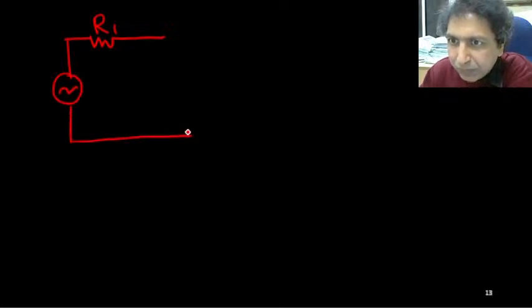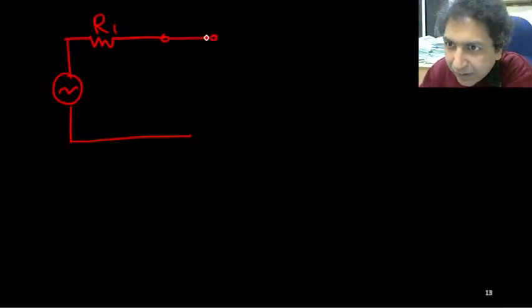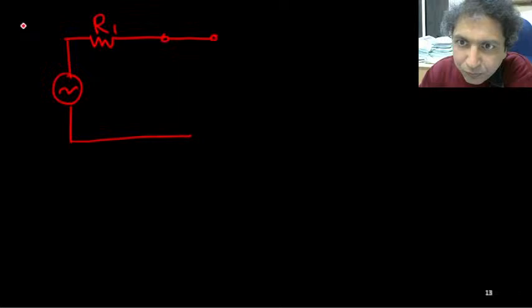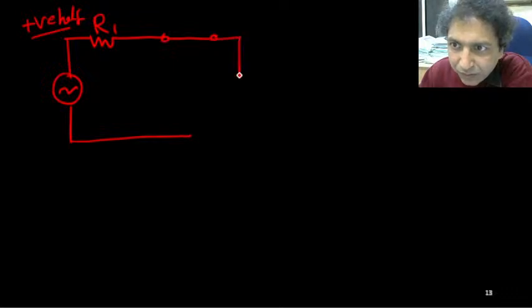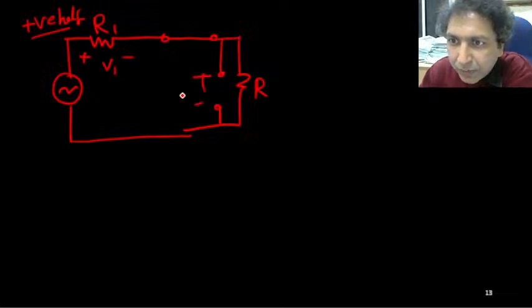This is your R1 and this is the input signal, and I have said that this diode combination, the parallel combination, is always shorted for both positive and negative. Okay. So now if I consider the positive cycle, positive half, and I will redraw this one for the negative half. So in the positive half, D3 is off, so this is off, this is also R. This potential is V1, this potential is V2.